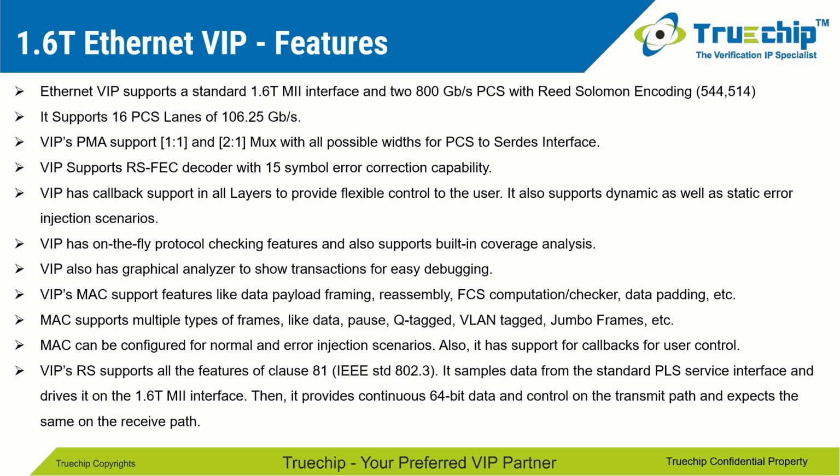The PMA of the VIP supports 1:1 and 2:1 muxing with all possible widths for PCS to SerDes interface. The VIP supports RSFEC decoder with 15 symbol error correction capability. VIP has callback support in all layers to provide flexible control to the user. It also supports dynamic as well as error injection scenarios.